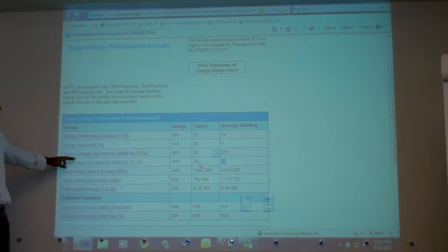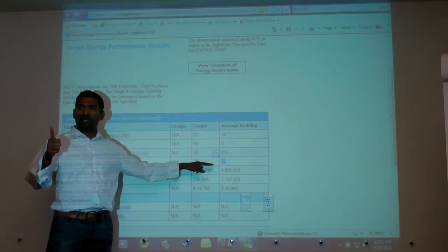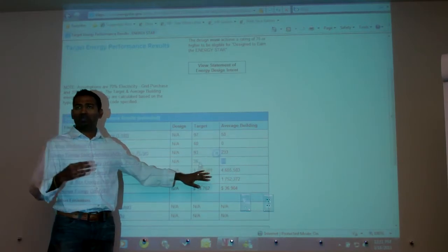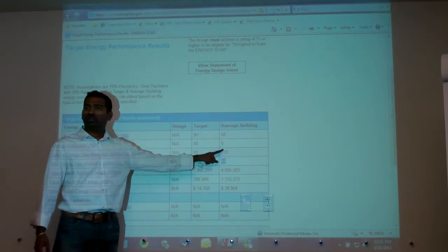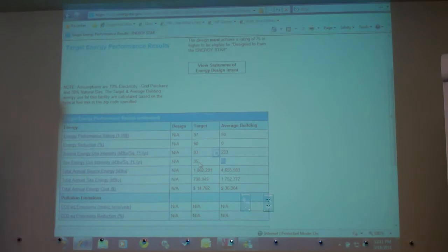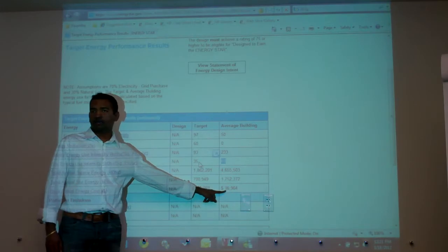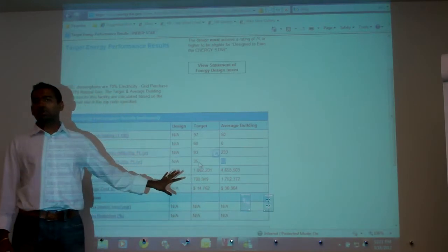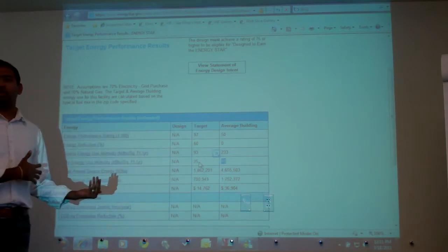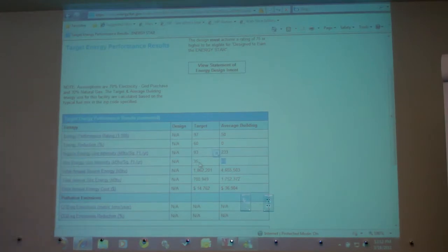You may notice that there's also the source energy use intensity. We talked about site and source last week. For typically electricity, it's 3 times, right? And this may also have natural gas. But look at how much energy is consumed at the source for this 88. It's typically 3 times. And it also gives us a rough estimate of how much annual energy consumption it is. So this is a great tool for early programming to understand what our average building's consumption is and how far we need to go down in terms of energy use intensity. Okay? Questions?